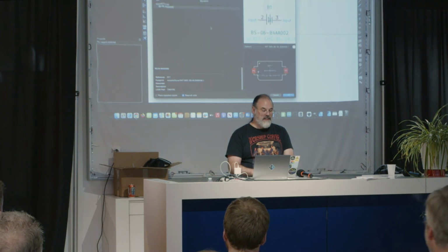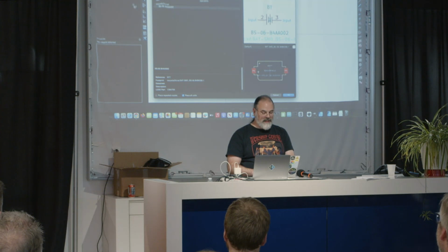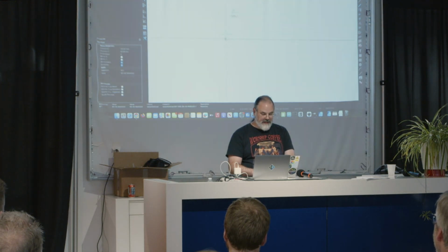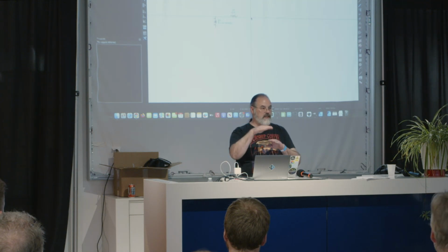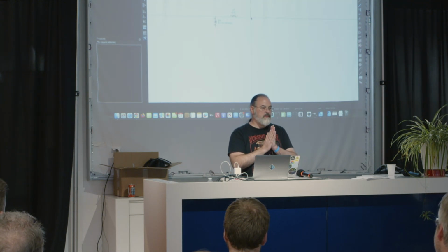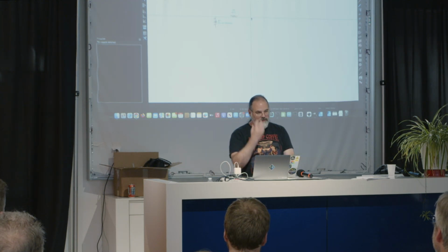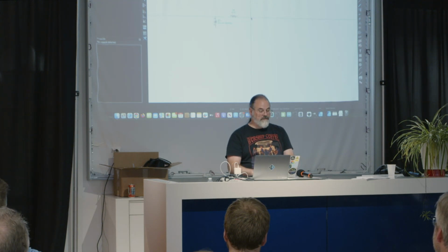All right, so I just pasted in that ID. It's already pulled it up here. So I can take that, drop that in here. We've got a battery. Now for LEDs, I started using side-lit LEDs on these PCB things, so I can put the LEDs on the backside and it'll kind of shine into the FR4 and create kind of a nice diffuse effect without blinding your eyes, which is totally fine, by the way, most of the time.